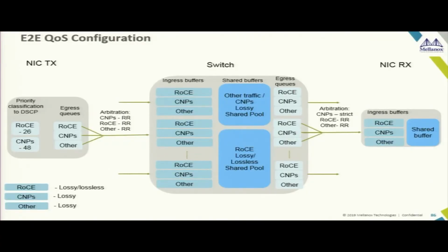And then comes a very important question. What if, because of congestion, my CNP, my congestion notification packet, itself gets blocked? Because physically it's sharing the same port and the same buffers. That's where you need the capability inside the switch to have multiple buffer pools, and again, this is all hardware architecture of your switching silicon. CNPs are characterized by a certain format, and they should be sent into a buffer pool which is not using weighted round robin, but a strict priority of 1. Like, please pass that across no matter what.